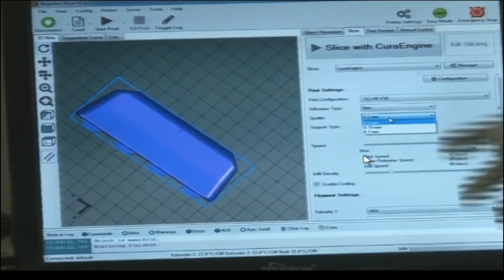And also, as I said, the quality and speed are countering each other. If the quality is higher, the speed would be lesser, because 0.1 mm and 0.2 mm, obviously the speed would be 50% of 0.2 if I use 0.1, okay, because 50% of the layer size is being deposited at each layer, at each slice.